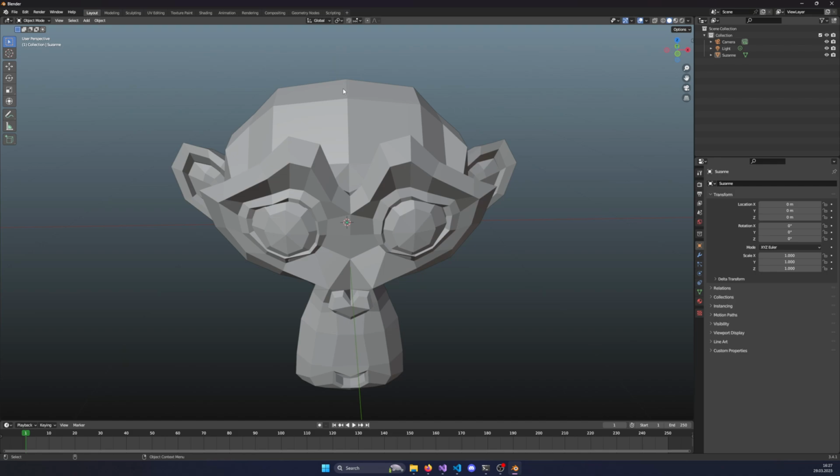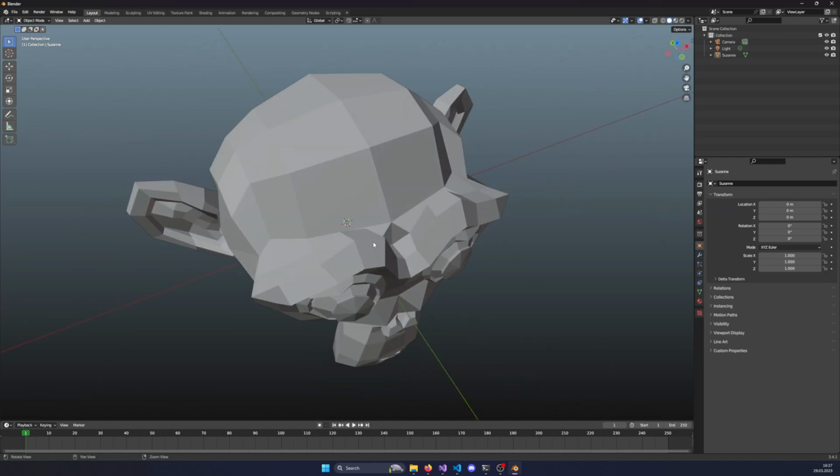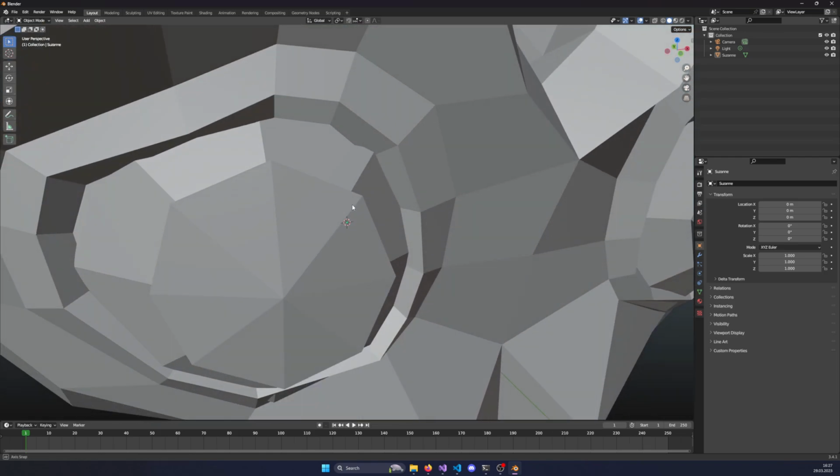However, it's a problem for us because we want to do real-time rendering, and for real-time rendering, we need to optimize everything. So we need to convert every mesh that we get into a triangular mesh, or at maximum a triangular mesh. Point clouds would be even better to use, maybe. But what we need is to have every mesh as triangles. Now, as you can see, Suzanne is not composed out of triangles. I mean, the eyes here, they are triangles. You can see there's a center point, and we have two other points, 1, 2, 3, triangle.